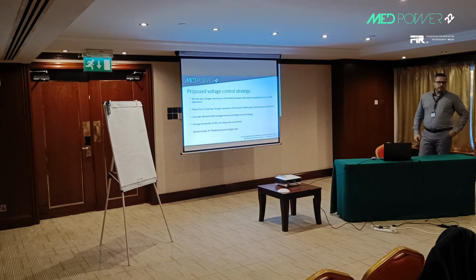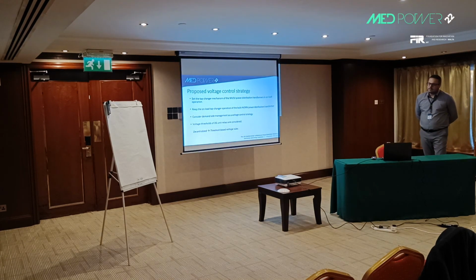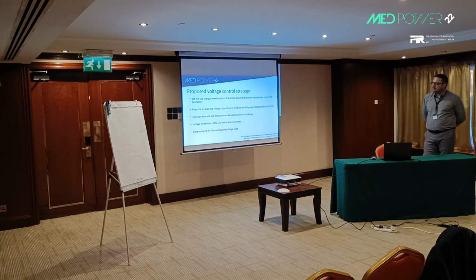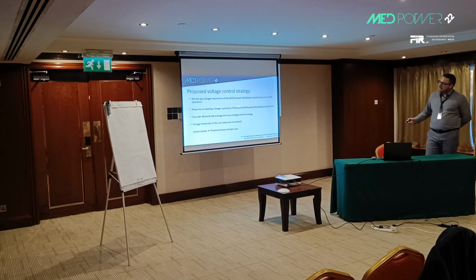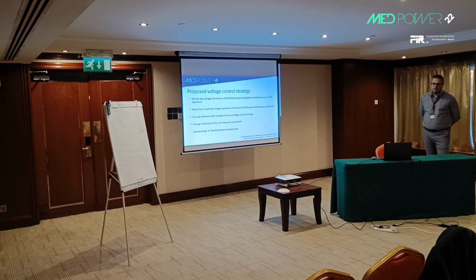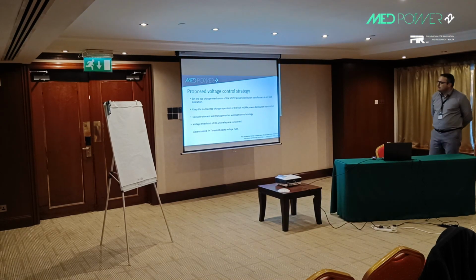In order to control the distribution voltage, we propose to enable the automatic on-load tap changer operation on the medium voltage, low voltage power distribution transformers of the distribution system, keeping, of course, the automatic on-load tap changer operation of the bulk high voltage, medium voltage power distribution transformer as well.